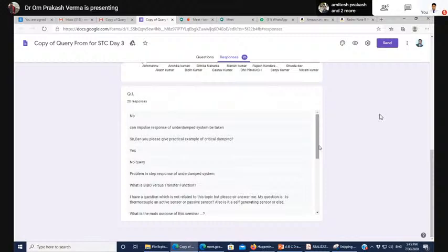That becomes some damper or spring type of problem. If you find the dynamics of that mass-spring-damper system, then you can find the transfer function of that second order system, and then you have to set the value of zeta.